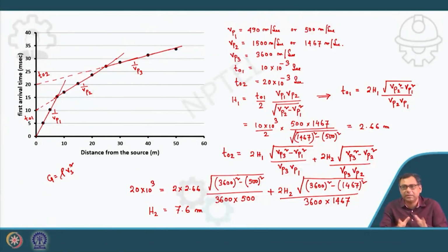Rho is the density. I have given this expression in my module 1. Similarly, if you measure the Vp, and you know the Poisson ratio, you will get the shear modulus. So ultimately if you measure the Vs, you get the shear modulus directly if you know the density of the soil layer, and if you measure Vp, you have to know the Poisson ratio of that layer.